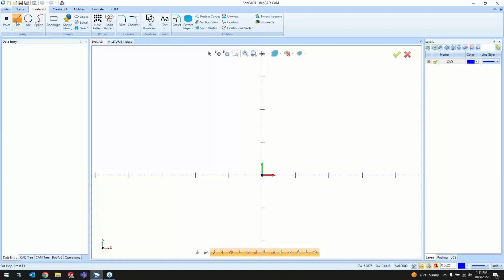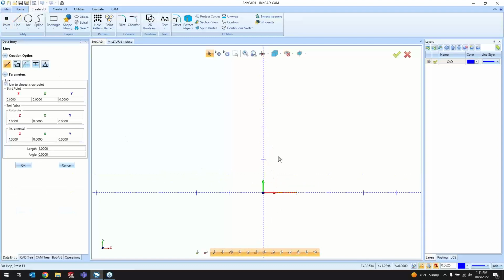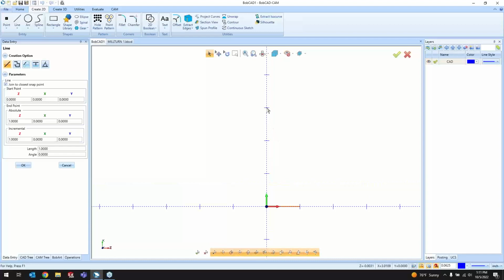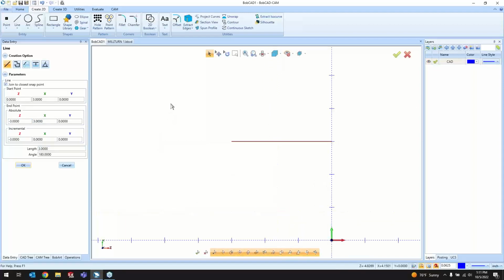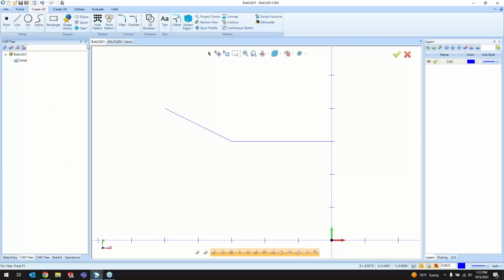So when I'm going in to create the outer diameter of the profile of the part, I start here at X3, Z0, and go backwards in the Z axis, and it will allow me to change that to -3, going out that way, maybe a taper outward in this direction, and I can change that start point that I had created here, maybe -5 and x4.